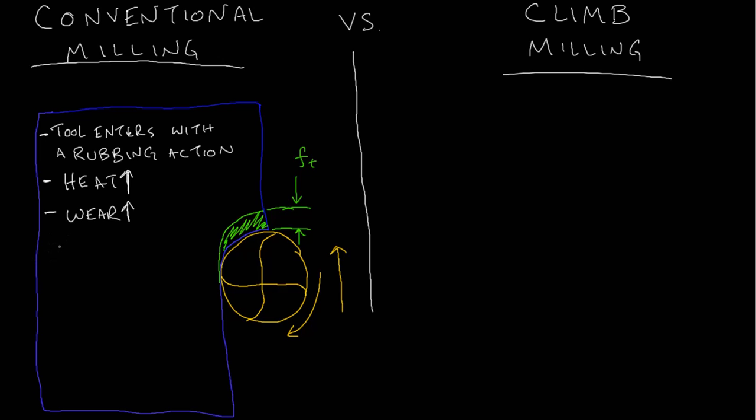And what this causes is the surface finish to look poor. So it'll be rough. It'll have wear marks. It just won't be smooth or it won't be lustrous. You won't get that luster that you get with climb milling. So the surface finish is poor.